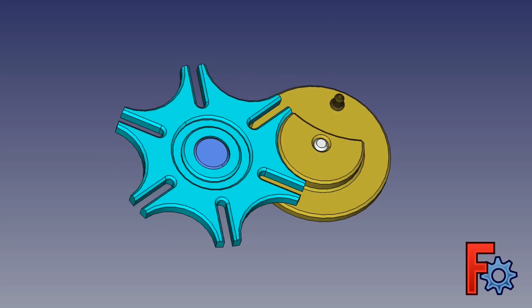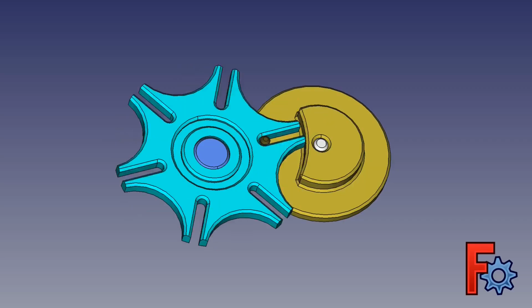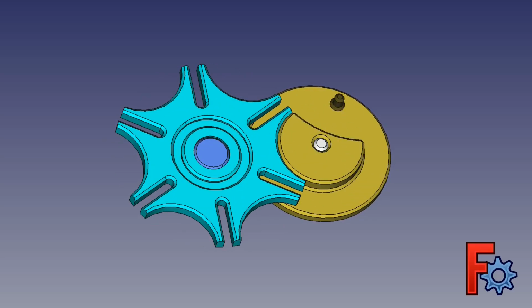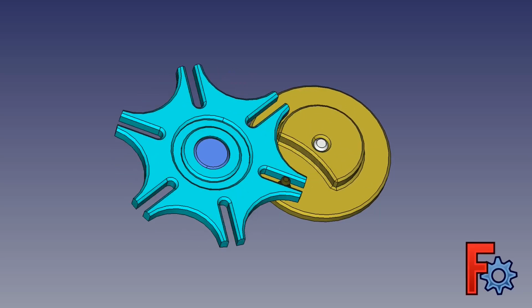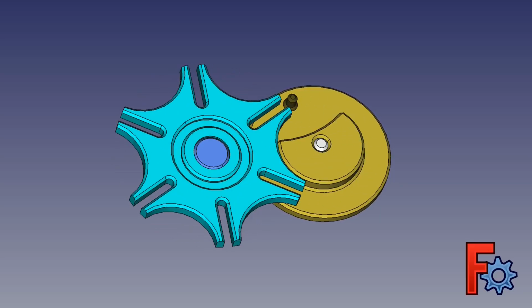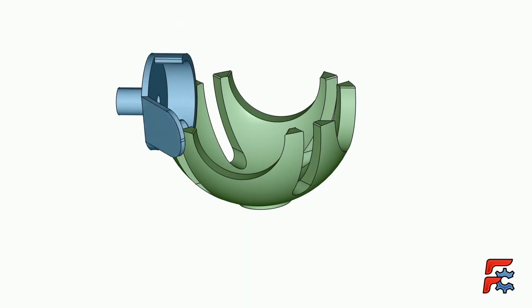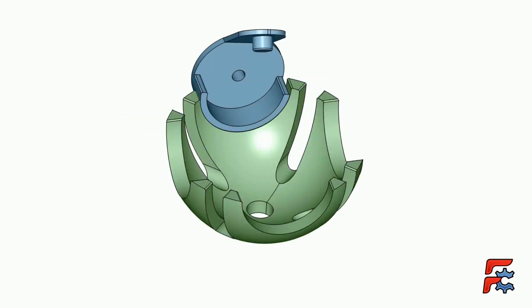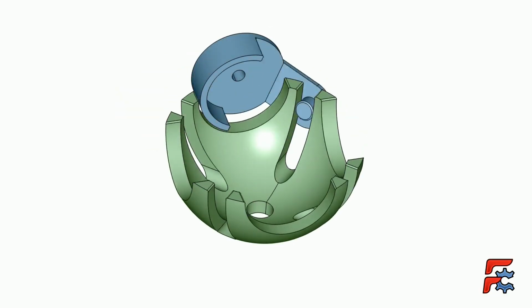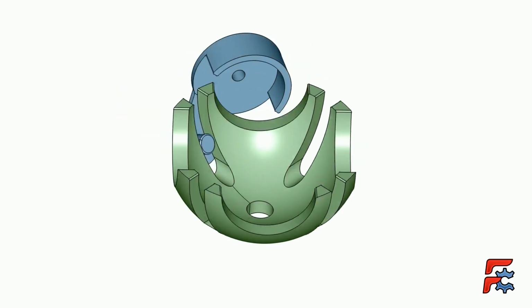The Geneva mechanism is a widely used device for producing intermittent rotary motion, characterized by alternate periods of motion and rest with no reversal in direction. It is also used for indexing, which involves rotating a shaft through a prescribed angle. In contrast, the Spherical Geneva mechanism is very rarely used. In the simplest form, the driven sphere has 4 slots and hence for each rotation of the arm, the sphere advances by one step of 90 degrees.